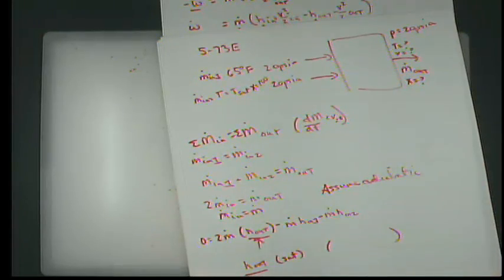So in other words, we're assuming that those two streams are mixing fully within the mixing chamber, and that on the outlet, they're going to be in mechanical equilibrium. I'm not really crazy about this problem. There's an awful lot of assumptions. I don't even believe it's going to be adiabatic, but you have to make that assumption in order for the problem to work. We don't have enough data otherwise. But if you solve for H, then you can go into the table at saturated water at 20 psia. Then you can solve for X. Does that make sense?